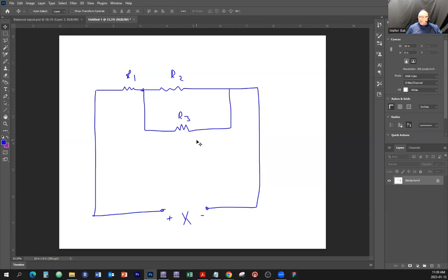And if you remove a component from the whole circuit and you still have the power on, the absence of this component could make the circuit behave completely different. And sometimes it can actually damage other components because it's not there. Okay? So we need to disconnect the power and we need to remove the component from the circuit.